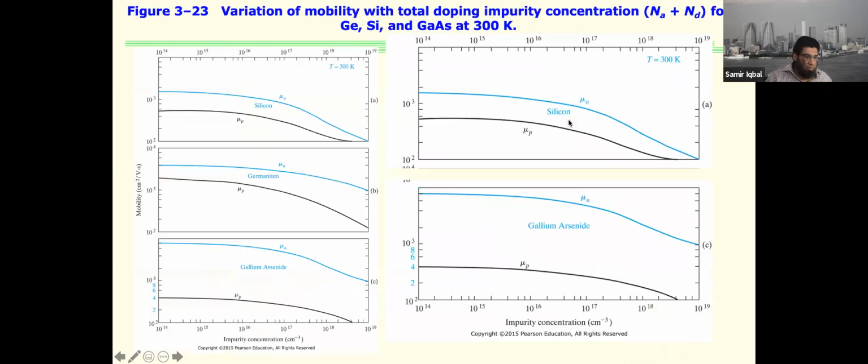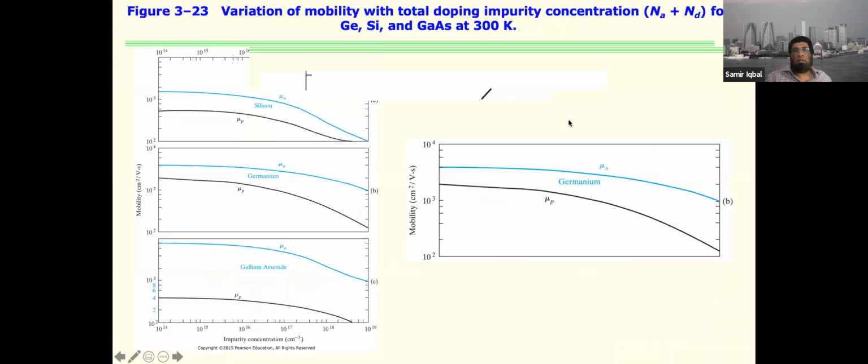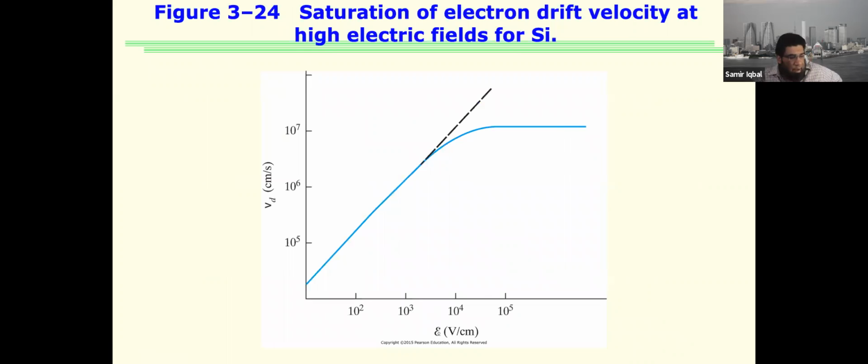Now when we talk about this region, this is the high field effect or hot carrier effect, where the drift velocity reaches an upper limit near 10 raised to power 7 centimeter per second for silicon. And in this case, the extra energy that you are providing from outside through the voltage is just being transferred to the lattice. It's just getting wasted there.